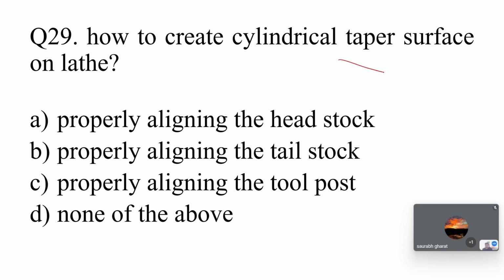This is the taper, as on the slides also. So you generate this kind of part. How can you do it here? The proper aligning of headstock is wrong. Only proper aligning of tool post is the correct answer.